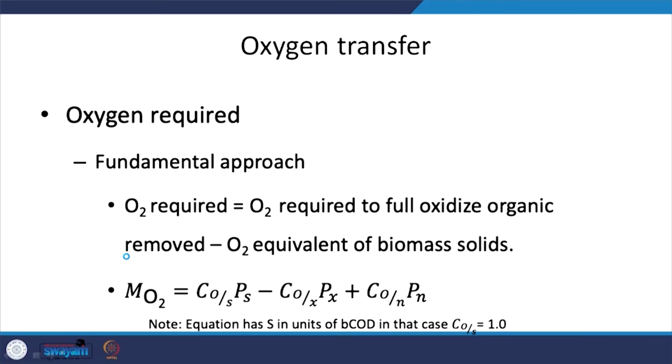The last aspect I guess is oxygen transfer, but it is pretty important. Why is that? In a wastewater treatment process, 50 to 60% of your maintenance costs are from pumping air in, right. Obviously BOD, oxygen demand, you do not want that oxygen demand to be exerted in the river, you want that to be taken care of in your wastewater treatment plant. So, you need to provide the oxygen right here.